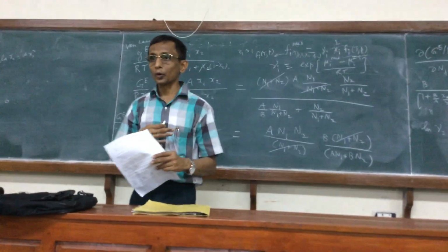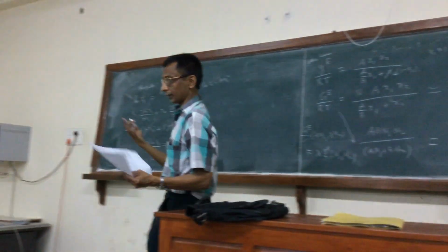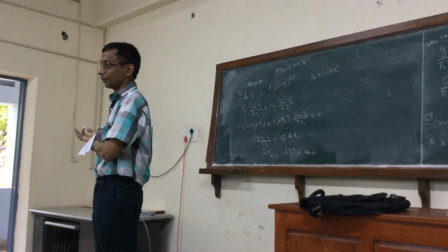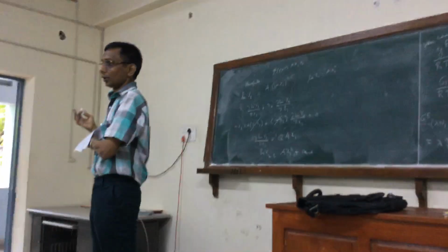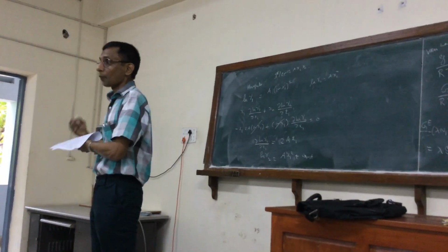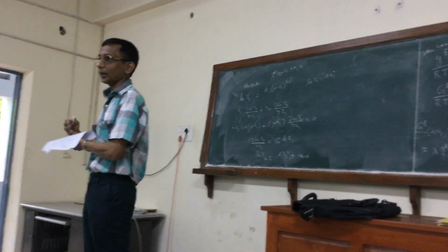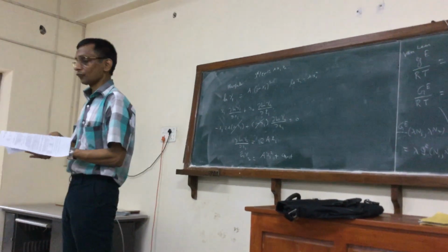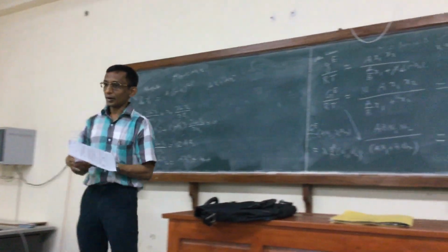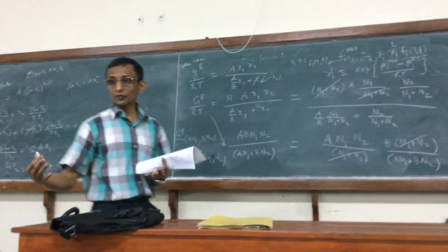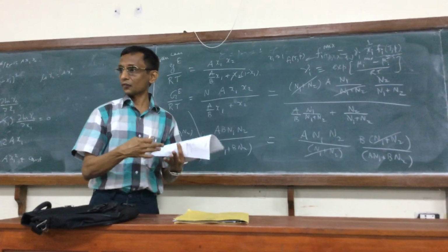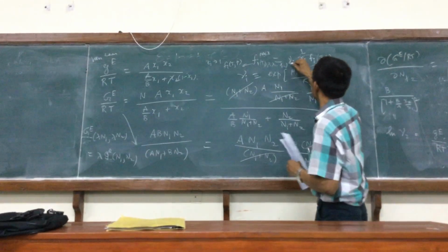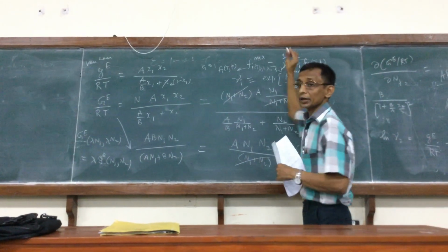Because we are getting to the pure component, in the mixture nothing will be there other than the pure component. So clearly we expect the fugacity of component I in the mixture to become that of the pure component, as all other mole fractions are going to 0 and the mole fraction of component I is going to 1. So clearly this will become Fi, and you can see that gamma I will tend to 1.